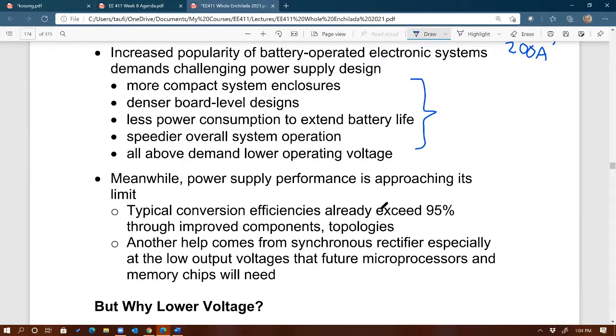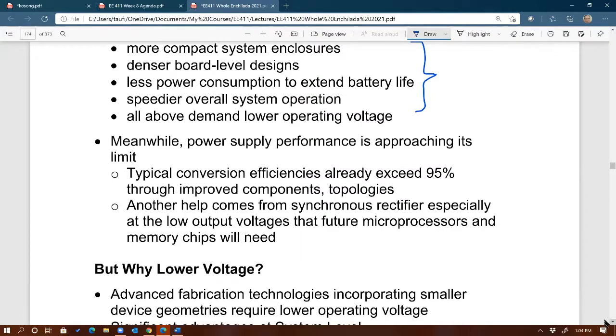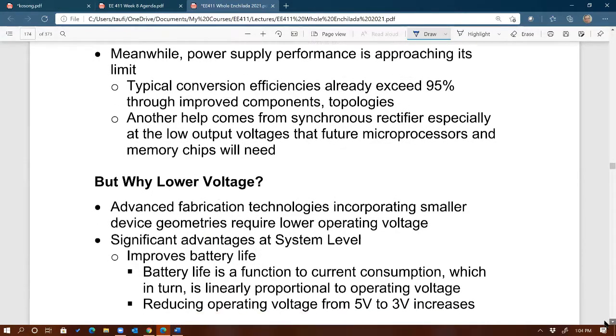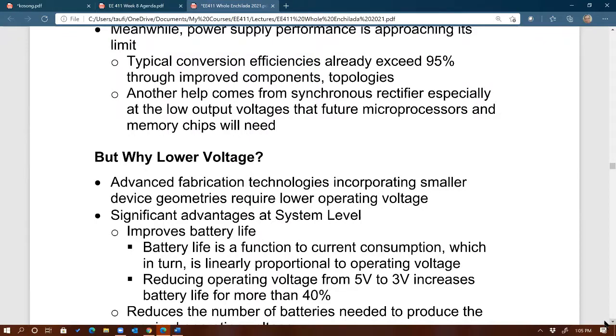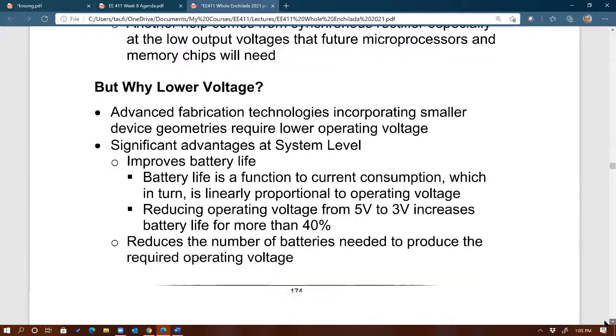And in order to provide this low voltage, the power supply to supply the power, namely the DC to DC converters, will also have to be able to output low voltage. And if we stick with our diodes in this DC to DC converter, then we're going to have a problem with efficiency. Does that make sense in terms of why a diode can pose a problem at low voltage applications, low voltage and high current especially? Yeah, that makes sense. Okay, good.